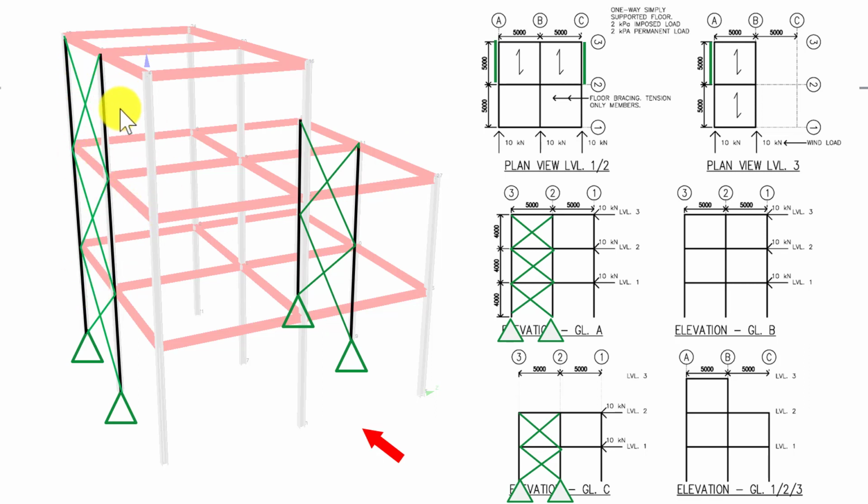Relative to the rest of the structure, it is virtually infinitely stiff because everything else we've assumed to be pinned, although in reality it's not. And this will now attract load towards it. However, the middle bay is still unstable. Grid line B, if I applied a load to it, would still fall over. So I need to add more to this structure to try get it stable.